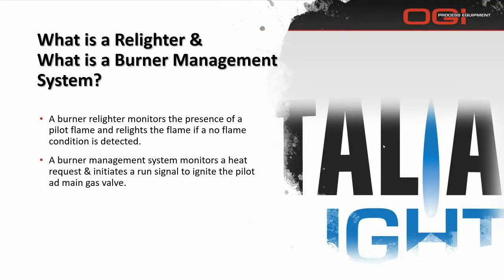On the other hand, a burner management system monitors a heat request that could be either a pneumatic temperature controller or an electronic temperature controller via a thermocouple. After it receives a run signal or a heat request, it will initiate the startup of the process, including purge cycles, and it will light off the pilot and consequently the main gas valve.